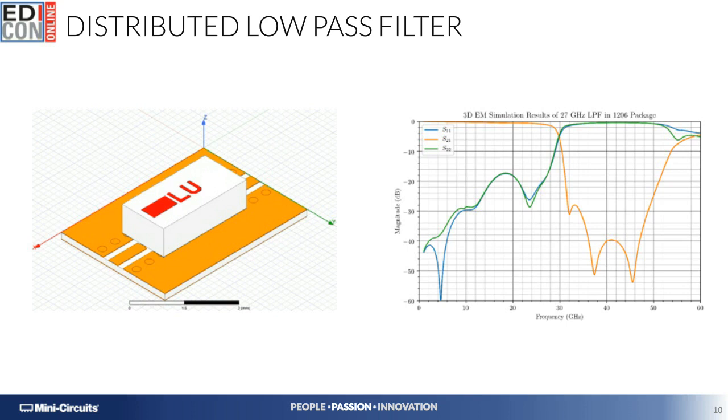These simulation plots also show much deeper and broadband stop band rejections, sustained performances at frequencies beyond X-band, and we may actually provide surface-mountable shielding structures to alleviate some of the needs that are required for deep stop band rejections at very, very high frequencies, above 30 gigahertz or so.